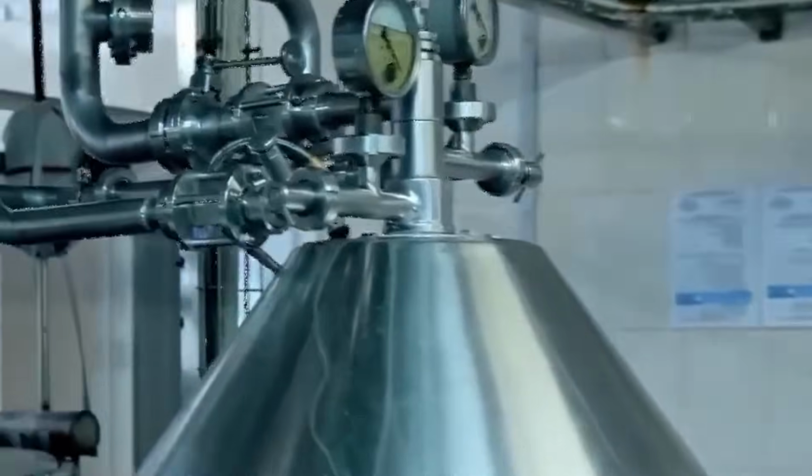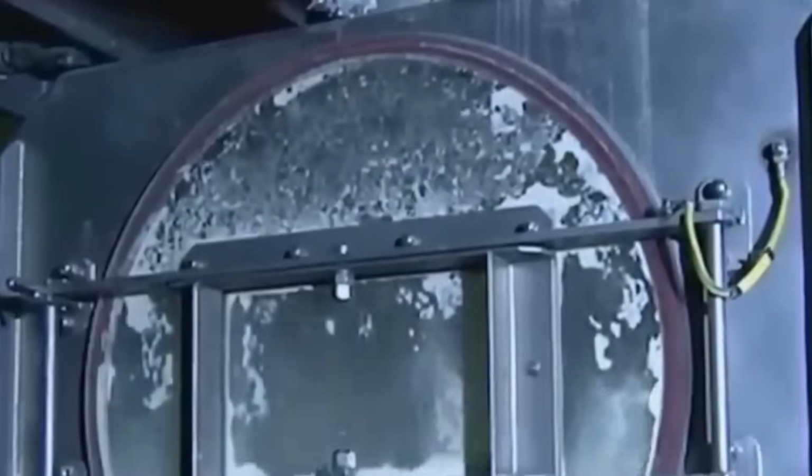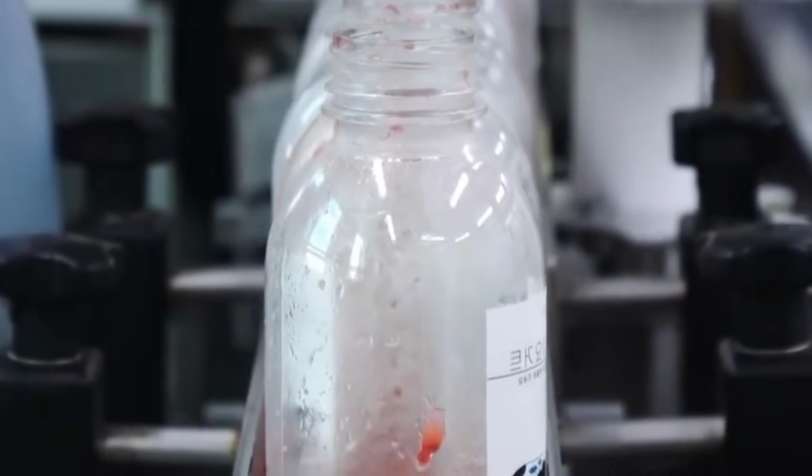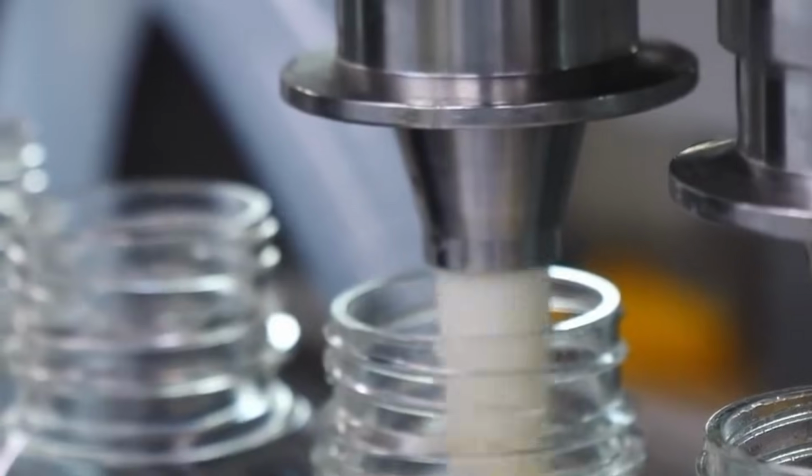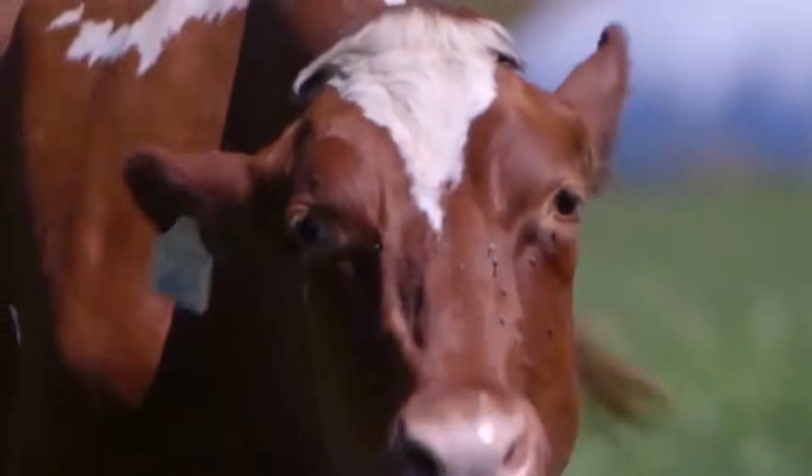Any batch failing to meet time temperature integration is automatically diverted to a reject tank. Following pasteurization, the mix is homogenized in a two-stage homogenizer at pressures between 1500 and 2500 psi. The first stage breaks down fat globules to sub-micron sizes, promoting a stable emulsion, while the second stage disperses protein aggregates evenly throughout the mix. Homogenization ensures a smooth mouthfeel, prevents cream separation, and enhances the stability of the yogurt base during frozen storage.